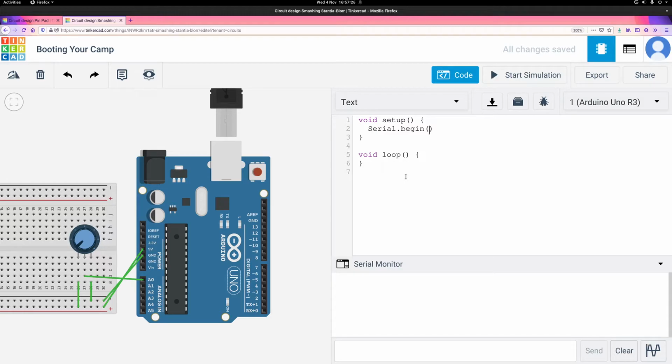This is called a baud rate. It's basically how many times per second it sends one bit of data, thereabouts. There are a bunch of different speeds that things can run at, but the most common one for Arduinos, when you don't need anything terribly fast, is 9,600. So this means they can send 9,600 bits in 1 second. In the real world, this speed is limited somewhat by your board. Different boards can do different fastest speeds, but 9,600 is very well supported, so it's hard to go wrong with that one.